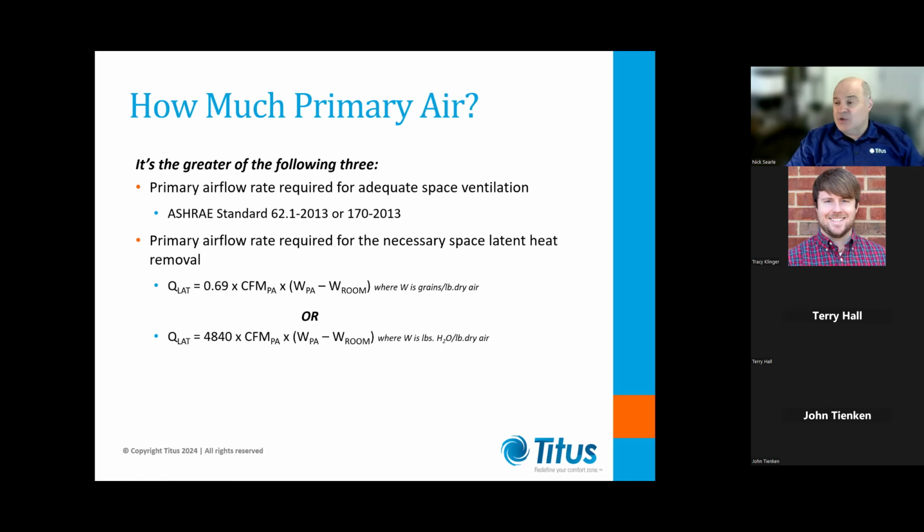it makes. So if you move from, say, 50 RH up to 55 RH, you may be able to save as much as 40% air in terms of CFM to the space. Most engineers that nudge this RH up stick to maybe around 53 RH and don't go above that. And that, again, makes quite a significant difference.